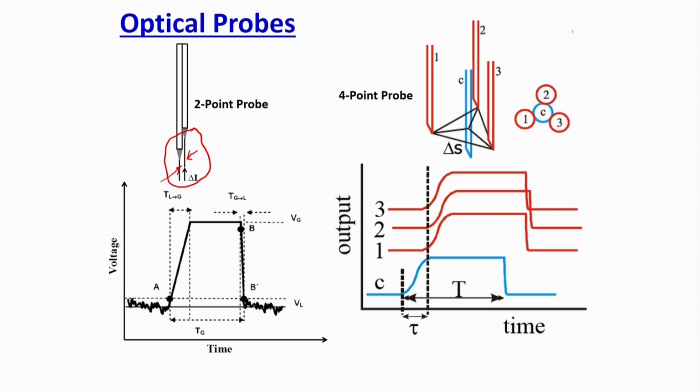So, suppose the flow is going from the bottom to the top; the probe should be inserted from the top to the bottom. This way the two needles of the probe should be inserted. Suppose a bubble is coming: this probe will see that the light will be refracted by this bubble. Once the bubble touches this, the refraction will be maximum.